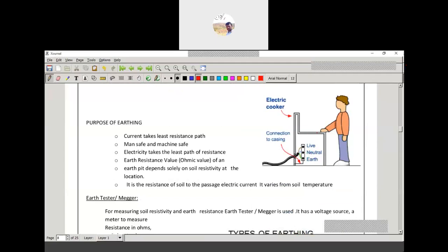So here we can see the H type cable. It has a metallic screen, belt conductor, and lead sheath. Here the cable has no insulated belt. The cable is further provided with the lead sheath, bedding, armoring, and serving. So we can see here we have the bedding, armoring, serving, lead sheath, and conducting belt, with paper insulation and metallic steel.